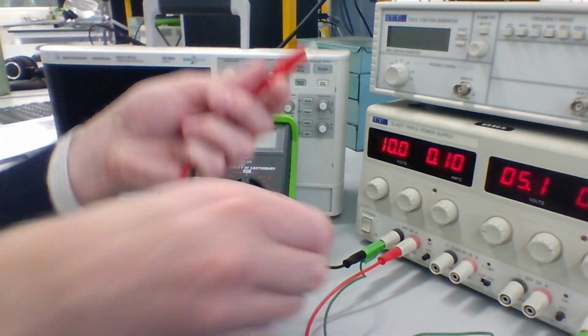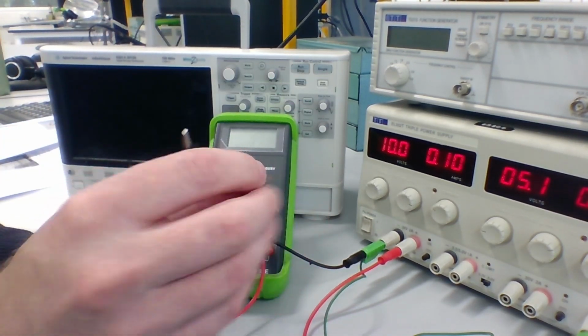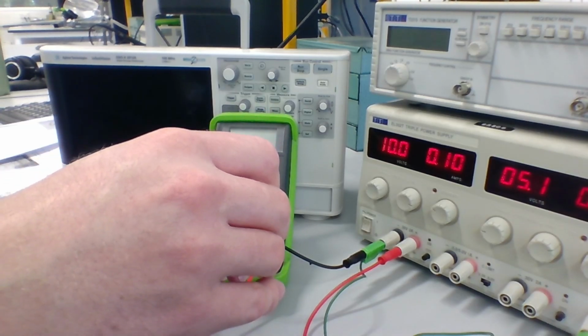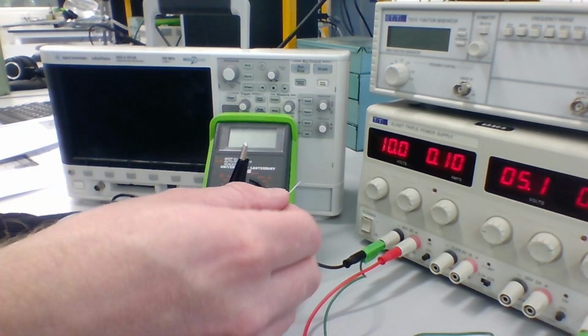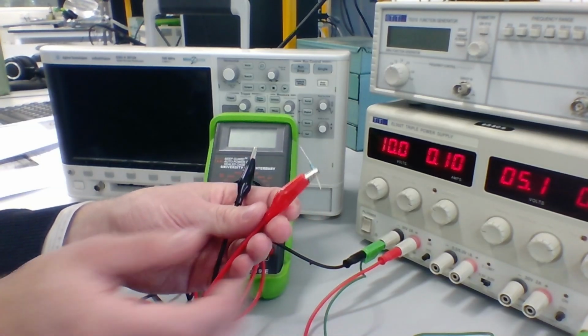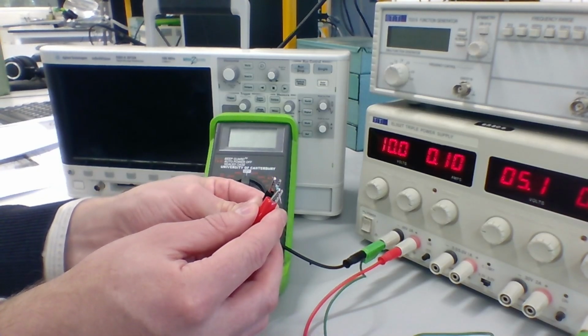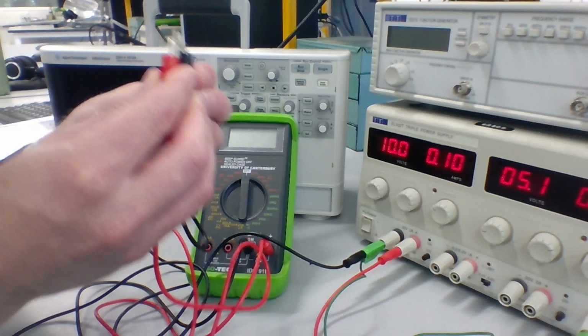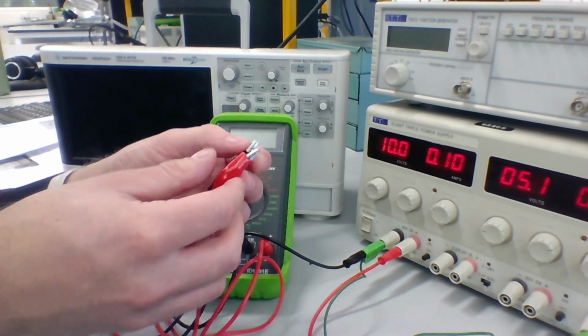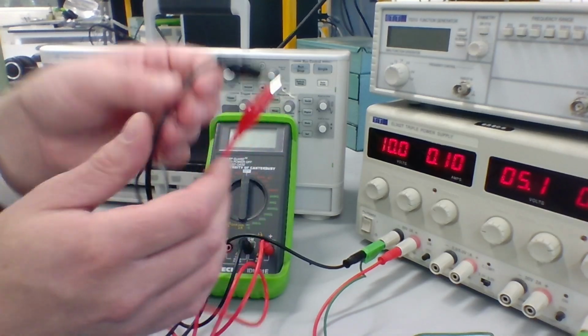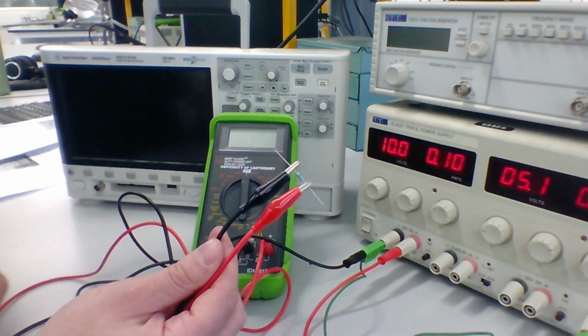I'm then going to hook these onto either side of the resistor, again using the alligator clips. And I'm going to leave a bit of space on the end of the lead so I can also connect the multimeter. So I'm going to connect these alligator clips reasonably close to the body of the resistor. Don't clamp onto the body of the resistor itself though, it is insulated and will not conduct. Okay, so now I have this connected up.